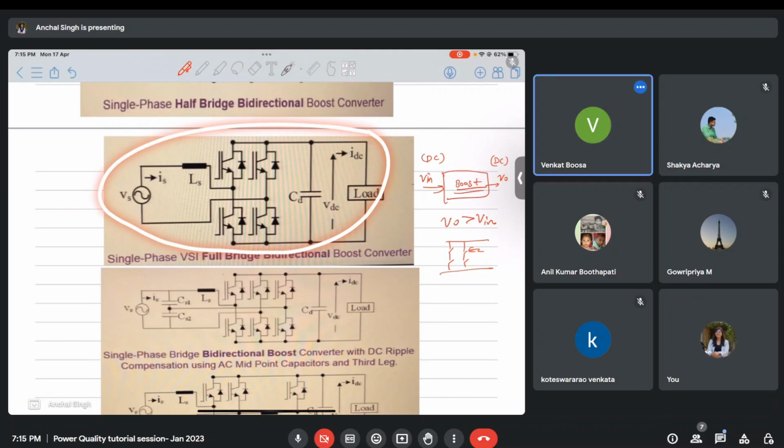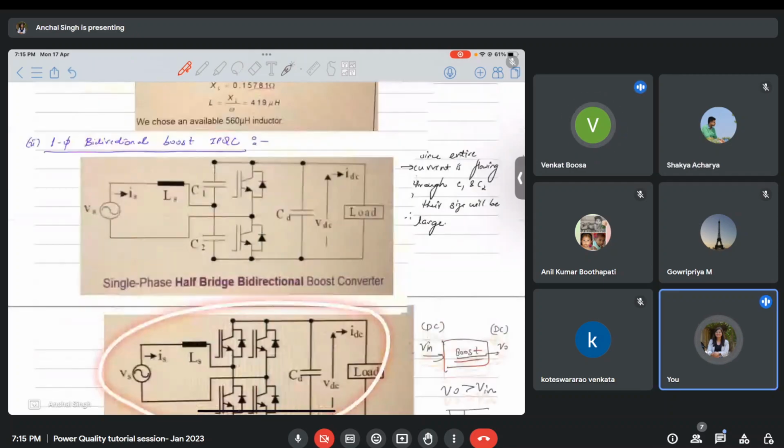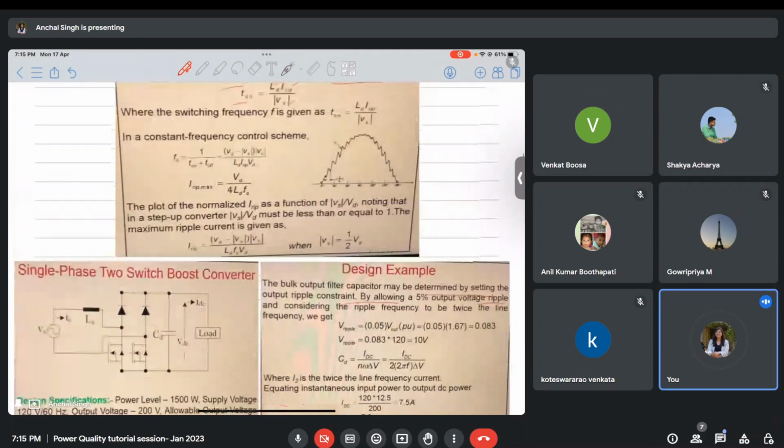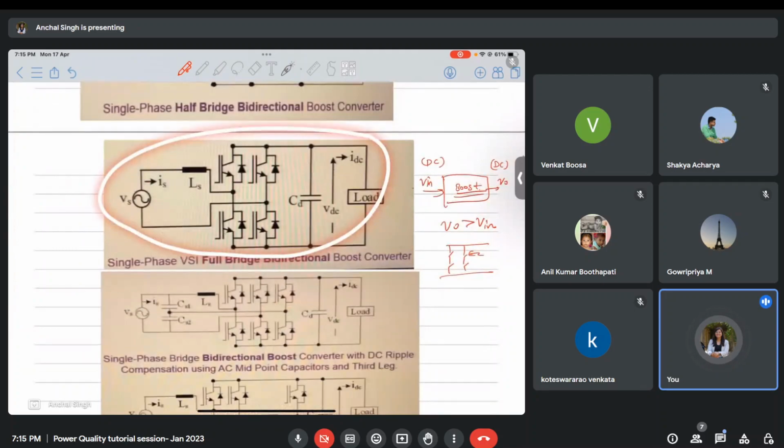Madam, are we using two circuits here, a rectifier circuit up to Vin DC, and then one more converter, a two-stage conversion? Yes, because boost converter is a DC to DC converter, right? So you cannot connect AC input here, right? You'll have to convert it into DC.